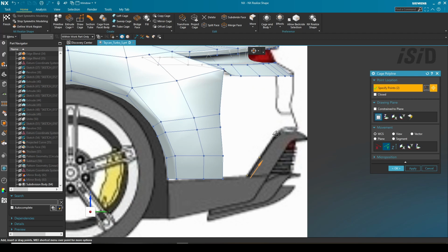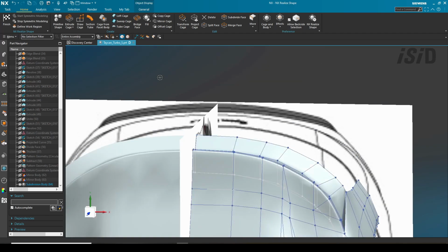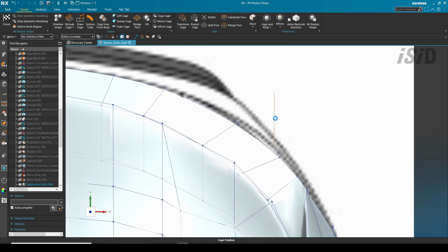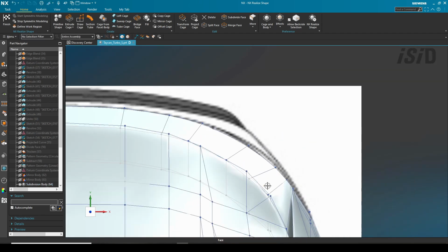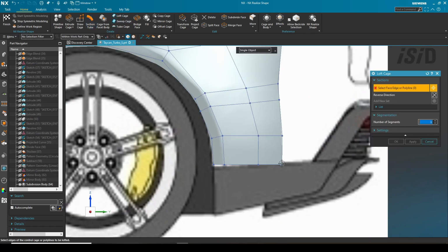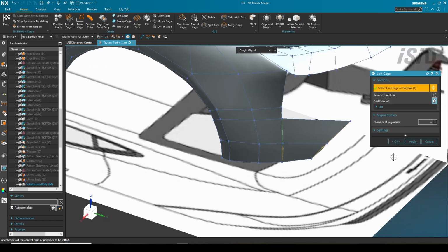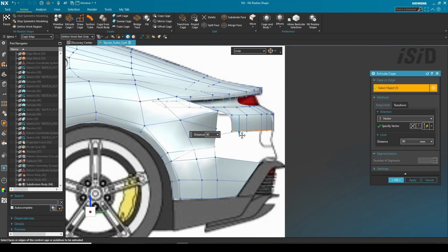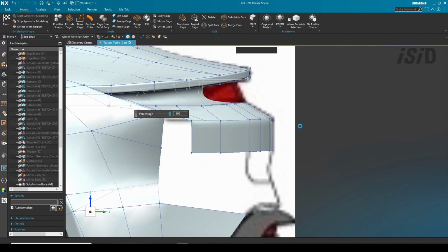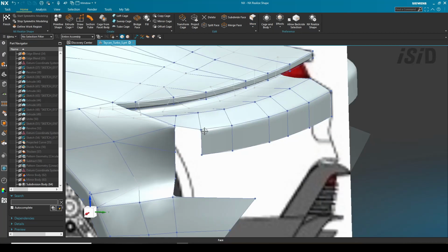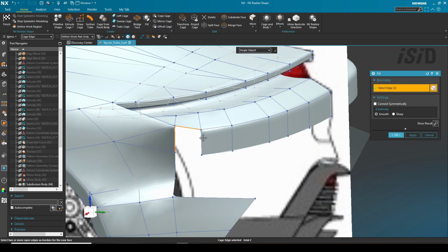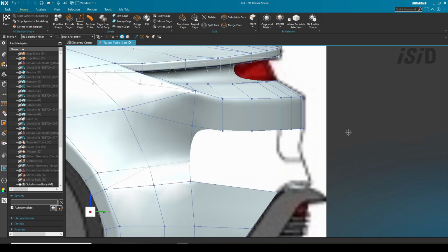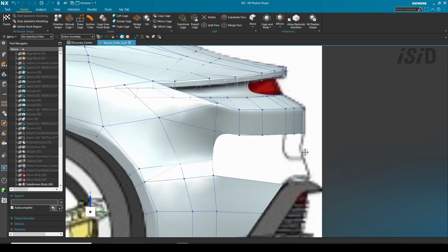And again, I need to create some cage polyline as the guide. And now I add more surface again using cage polyline here as the guide, and add this surface by using loft cage or sweep cage. And this one I add more surface using extrude cage downward, and fill out the surface using fill surface command.